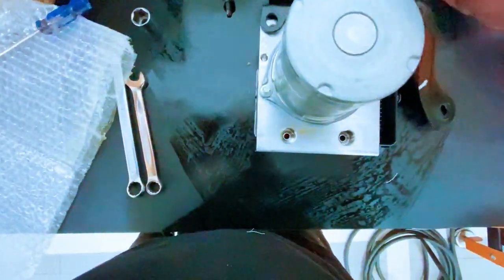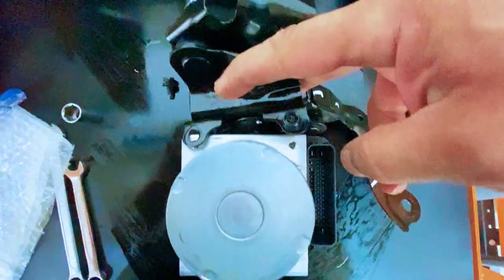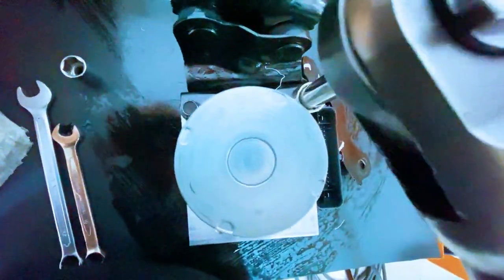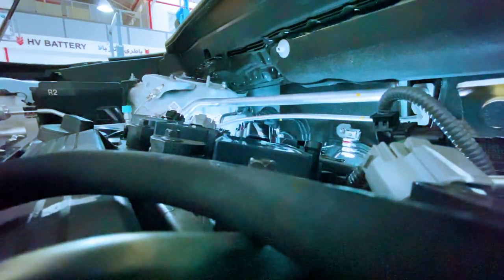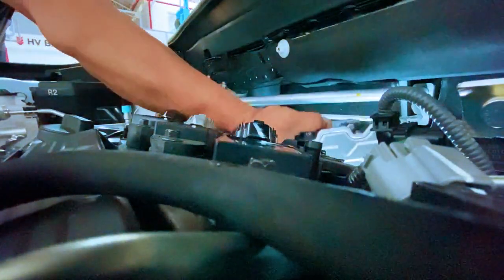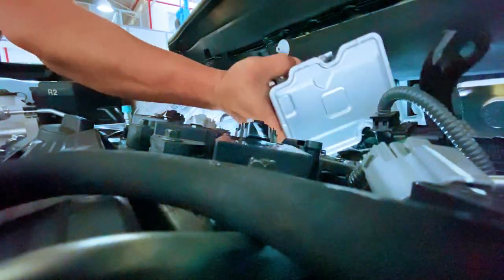The electronic parking brake communicates with the brake control system through the skid control ECU. If the brake actuator has a serious internal or electrical fault, the system may not correctly process or compare the EPB switch signal. As a result, C060962 can appear together with the primary ABS DTCs. This means we should not immediately replace the EPB switch just because C060962 is stored. First, repair the primary ABS or brake actuator problem.